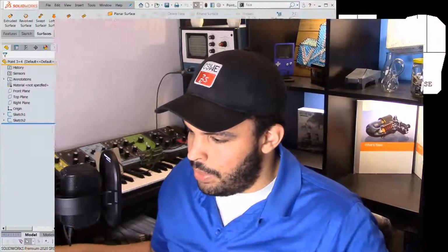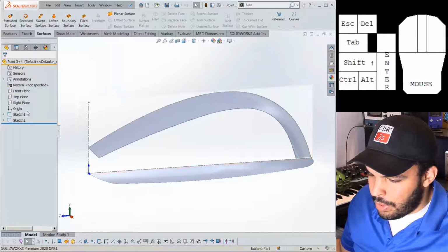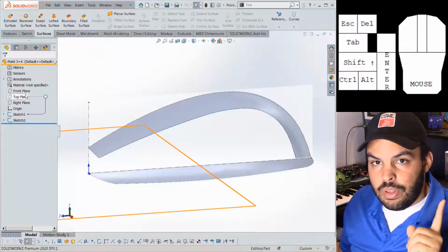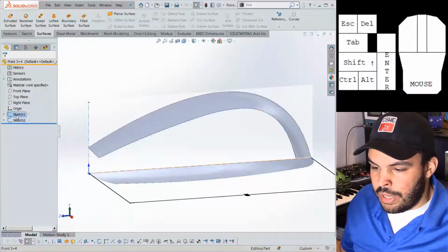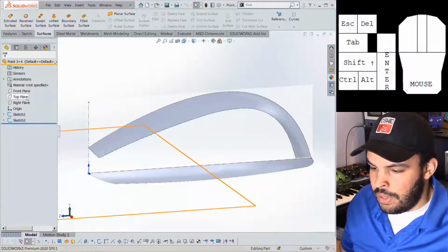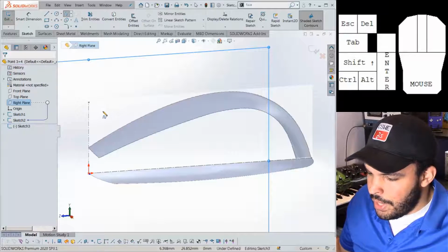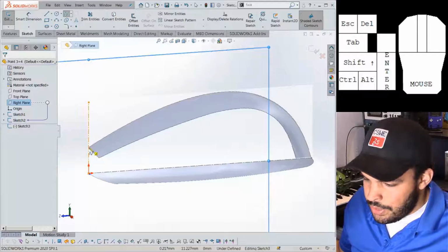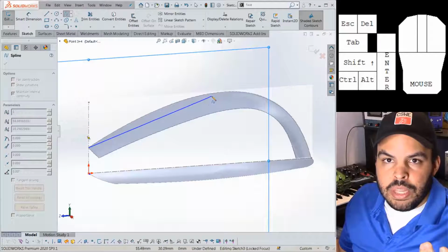So for example, if I wanted to trace out this top curve here, another point of information: do not sketch directly on the sketch picture sketches, make a new sketch. I think I mentioned that in many of my other videos of this nature. But basically, to trace, you place a point right at the end point, and then you're just playing hills and valleys.